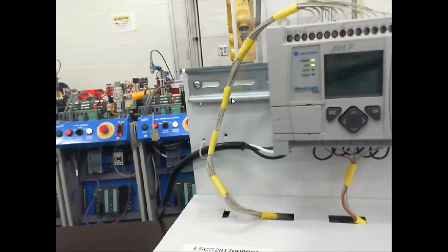When you hit e-stop, it drops out this relay, by the way. So e-stop buttons have to be hardwired. They can't be programmed. They got to be hardwired, because programs can crash. I know every once in a while your phone screws up. You tap on the front, nothing happens, and you turn your phone off or do a reset on it, or you exit the application and bring it back up. If it works, that's okay on a cell phone. That's not life and death.